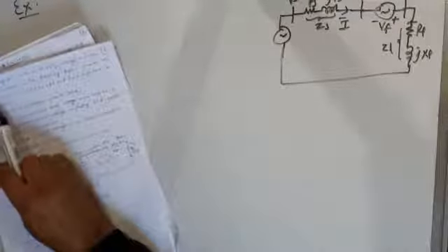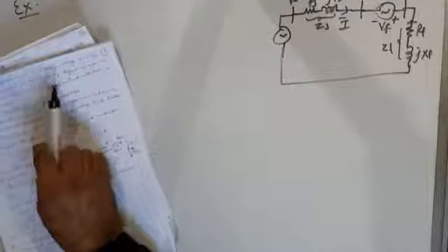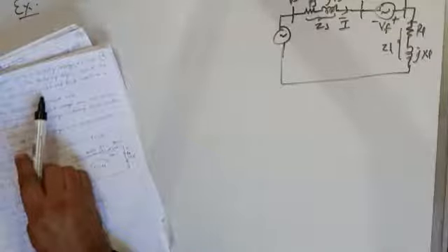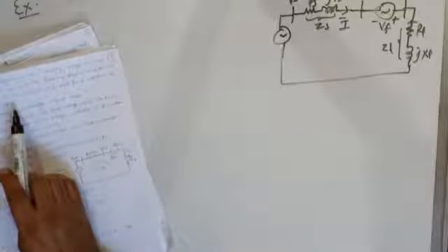Consider a system with a supply voltage V equal to 1.0 per unit at 50 Hz as shown in the following figure. This is the figure. This is DVR compensated distribution system. Consider the feeder impedance Zs equal to 0.05 + j0.3 per unit, and load impedance as ZL equal to 0.5 + j0.3 per unit.